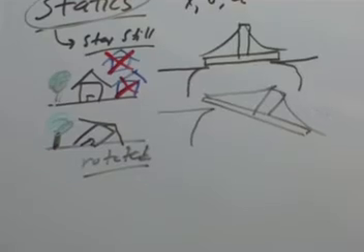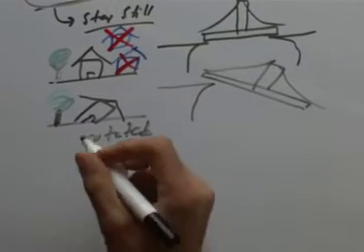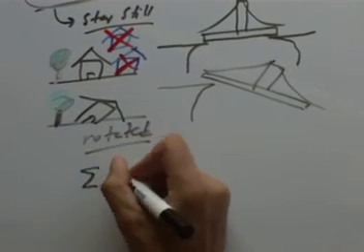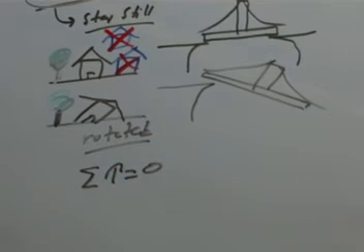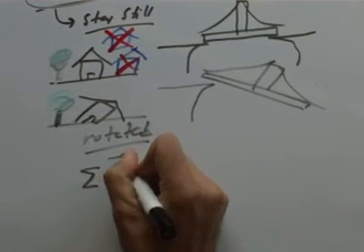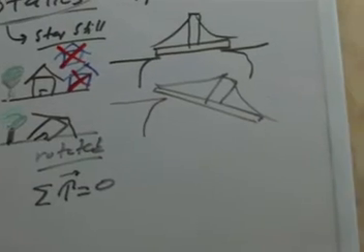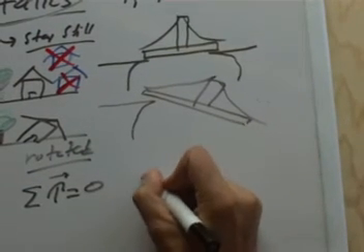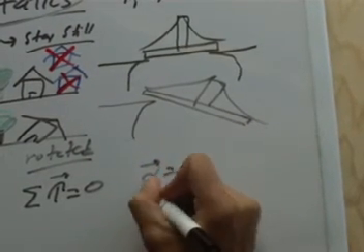And the way you ensure that is an equation very much like the sums of the forces, but what you want to ensure now is that the sum of the torques are equal to 0. Torque is technically a vector in there. Now, where does this equation come from? Well, what it's really saying is you want the angular accelerations on all the objects to be 0 as well.